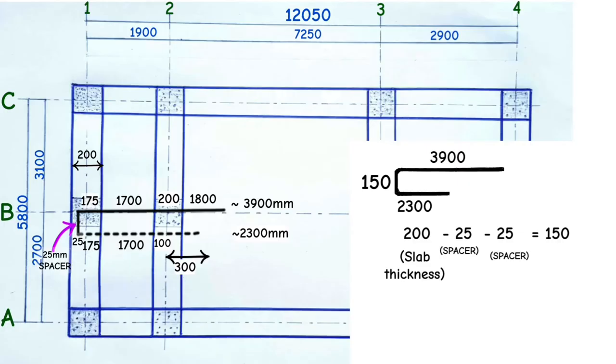These steel bars will be covering this inner surface distance from grid line A to grid line C. Therefore, this inner surface distance is 5.6 meters, and for every distance of 5.6 meters, we need 40 steel bars, which will be fixed from grid line A to grid line C. Let's describe this steel bar shape now.